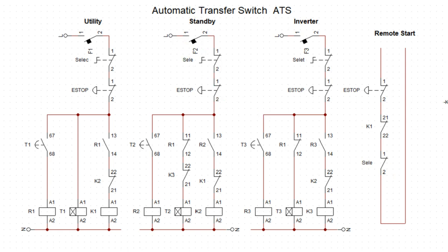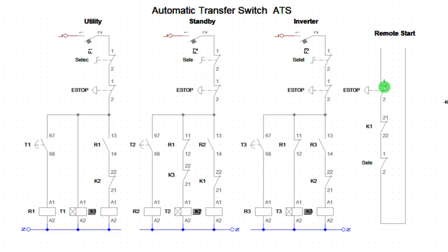If I operate the emergency push button, just look at the whole of this place will open. Once I operate it like this, look at four of them open. The genset will shut down. Look at it. Now, that is the one means of shutting the genset down. Then, if here also opens, that is if mains contactor closes and here opens, the genset will shut down.